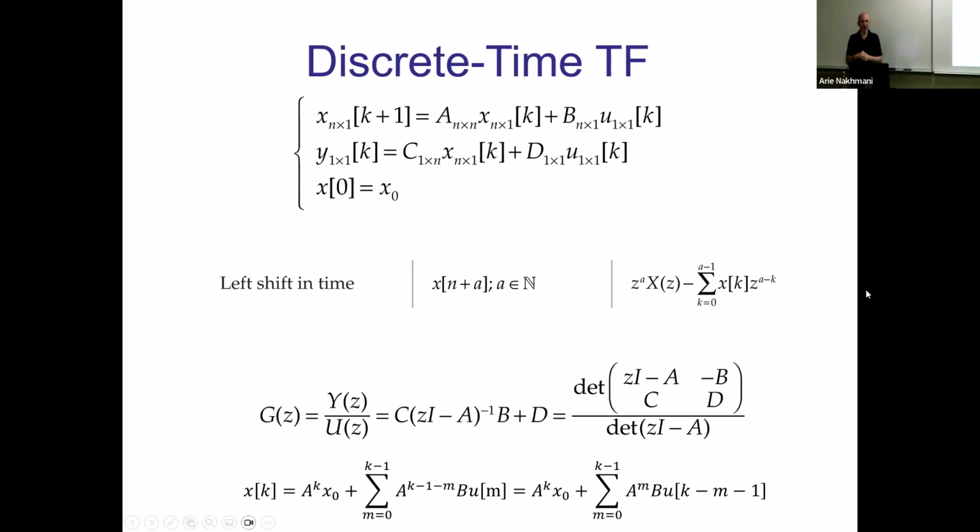All right, so this is the discrete time case. If your system is discrete time, which means it has time steps, a sampled system, the representation is exactly the same. And I prefer indices of time to be in rectangular parentheses, and most of the textbooks are using that. But sometimes you also see representations where you have subscripts as index, like x of k plus 1 as a subscript k plus 1, okay? But since I'm using subscripts for dimensions, I don't want to mix them. This is the reason why I'm using rectangular brackets for the time index, okay?